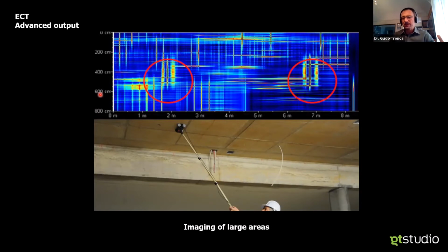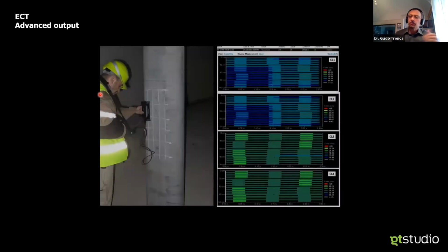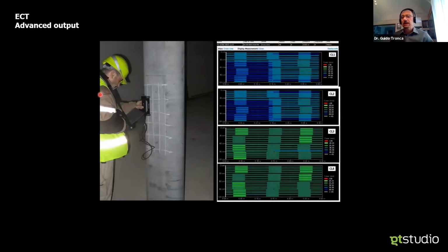The same measuring principle can be used for broad slabs or soffits or small elements. These are typical reports that an NDT company could deliver when asked to perform rebar location on single objects. Color-coded mapping in terms of cover or diameter, just to give an overview of this.